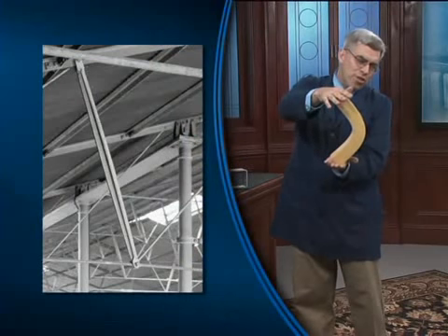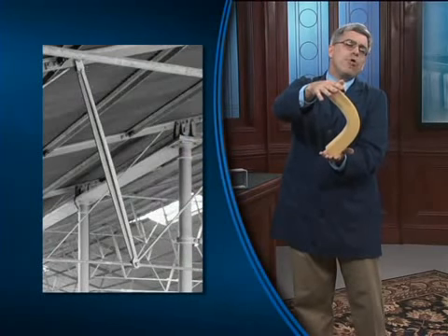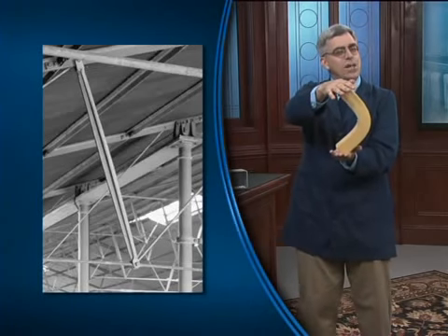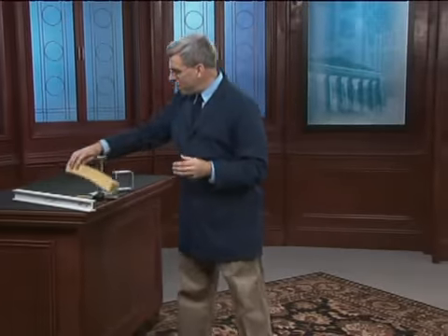And since it bends more in the center, it has greater need of resistance to bending out near the center than it does at the ends. So it makes perfect sense to make the column thicker in the middle than it is out near the points of support. Effectively, what Badger and the designers of the Beijing Capital International Airport knew was that you should give the column the most resistance to buckling at the point where it's most needed.